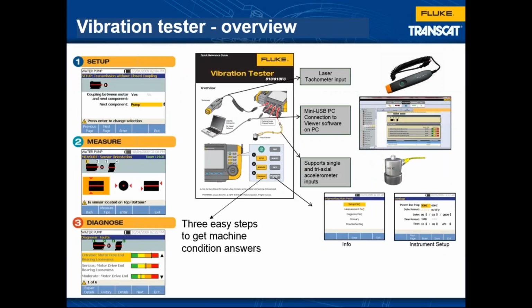The vibration tester, like a doctor, is going to ask questions about the machine and take some further tests to find out what the fault is. So think of it like an EKG. So we're going to take some frequency data. There's 3 simple steps: setup, measure, and diagnose.